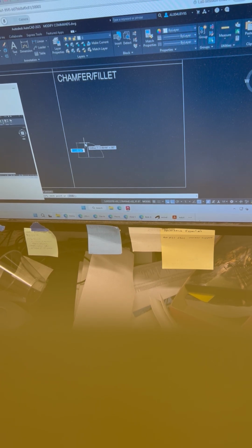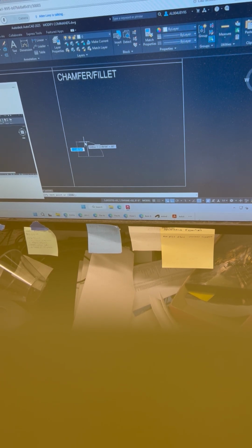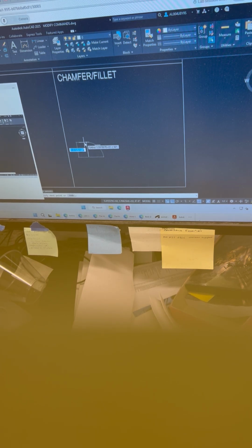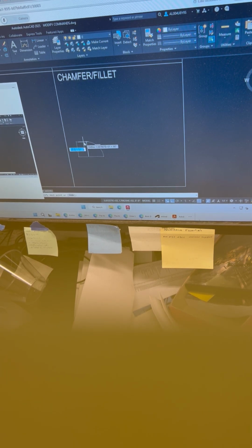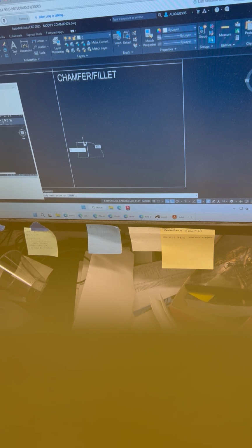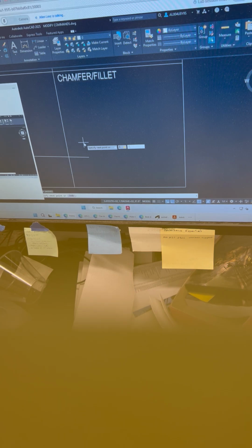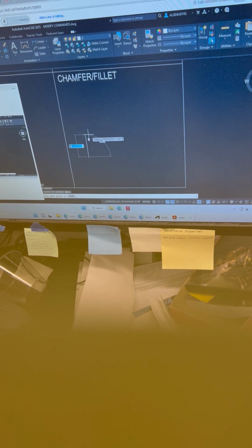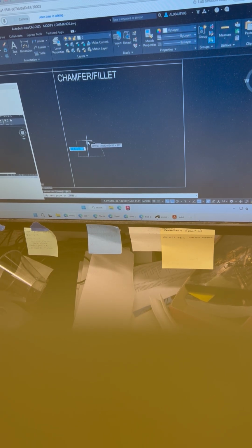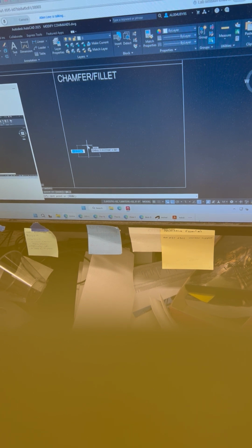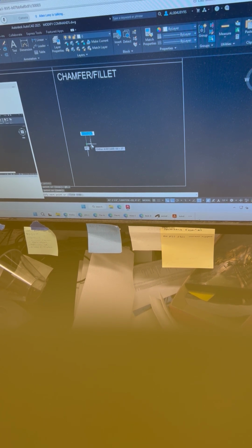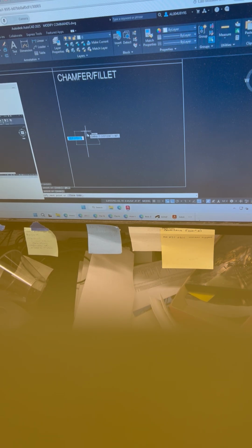Here's the polygon tool. Go ahead and start that command. For the number of sides, I'm going to go ahead and enter in, how about 5 sides? We'll make a pentagon. Go ahead and put in 5 sides and hit enter. Next, it wants to know where the center of the polygon is going to be. I want you to pick the bottom of the first line, the end point of the bottom of the first line, as the center of your polygon.